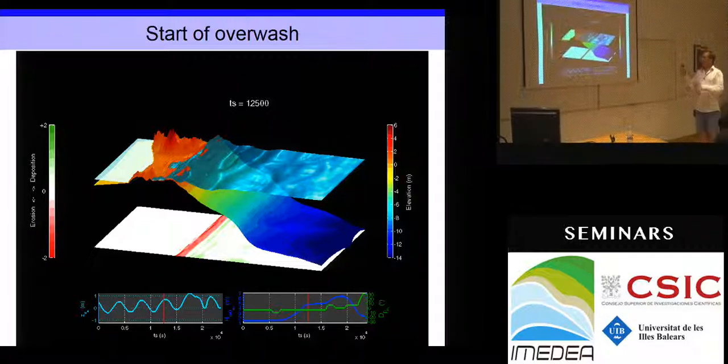And what you see here is actually a snapshot of the surface elevation, but this is the surface elevation of the infragravity waves. So this is not the individual waves, this is just the infragravity waves and the mean water level. Waves are coming in from the Gulf of Mexico. This is the barrier island. And below here is actually a depiction of the sedimentation and erosion. So red is erosion and green is sedimentation. This shows the surge level. So this is tide and wind.